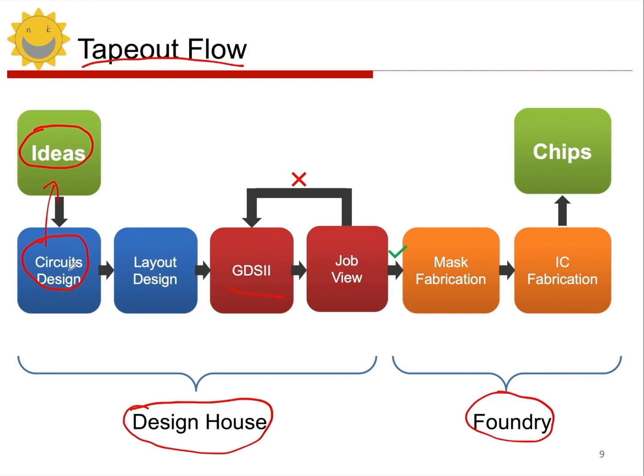After that, we need to turn the design circuit into a manufacturable blueprint, which is essentially the layout design. We use a multi-layer drawing method to convert the design circuit into a layout. Once the layout design is complete, it generates a GDS2 file, which is the format most commonly used today. This file is then delivered to the foundry. So, the key link in the data handoff between the design house and the foundry is the GDS2 file. Typically, when we deliver the GDS2 from the design house to the foundry, this process is known as tape-out.